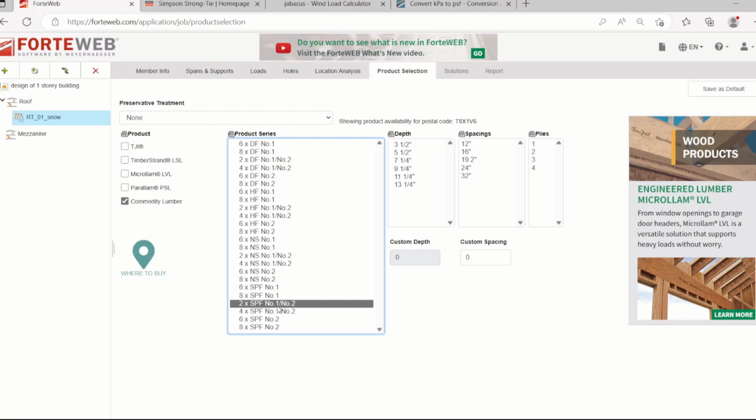All you have to do is, say in a truss you have a bottom chord and then you have a top chord, right? And if you want to get the actual dead load of the truss members, then all you have to do is use, say, your member is 2 by 6. And on the spacing, even though the roof trusses are spaced at 24 inches on center, because we are only calculating this for the purpose of getting the reaction, we'll just use 12.